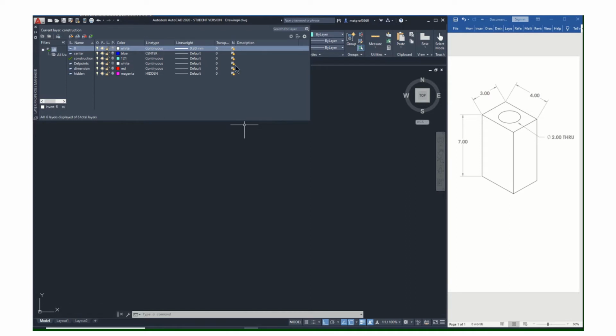Depth points is a layer that is automatically going to show up. Don't draw on that layer. See how the printer function is turned off? That's kind of like the layer that all the garbage goes into, so don't use that layer. Create a dimension layer. It's red. It's continuous line, default line weight. And a hidden line layer, magenta, loaded the hidden lines, default line weight. Okay, we've done that before. There's a video on how to do that.